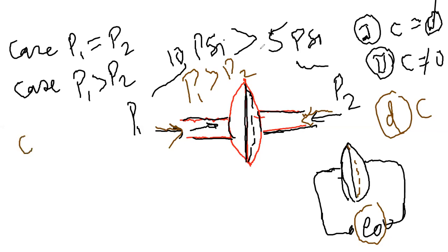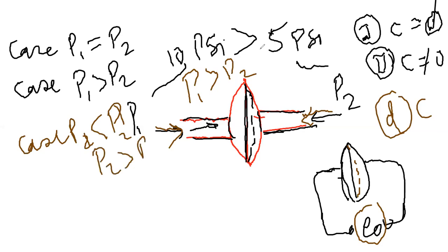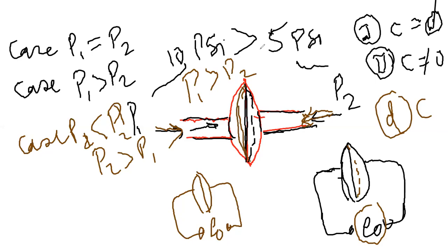Okay. The third case is that if my P1 is less than my P2, meaning P2 is greater than my P1. At this moment, what is going to happen? This is the structure of the plate. From here, I have taken the resultant output E0, and this is the plate. When I am applying a pressure from this side, no doubt the deflection will be towards this side, resulting in the output of E0. So this particular E0 will be the output that has been generated for the capacitance 1. This change in capacitance is calibrated in terms of